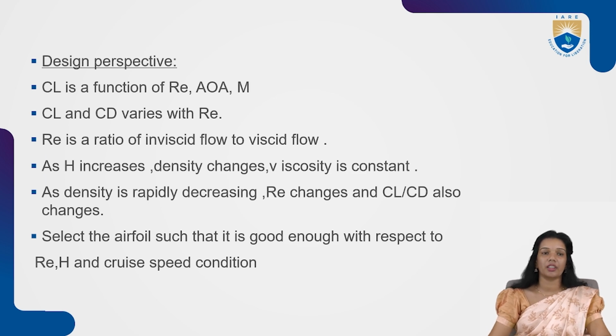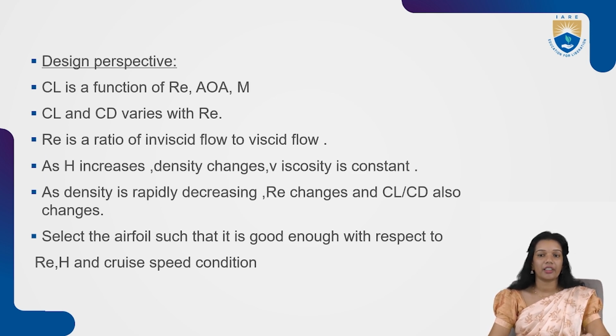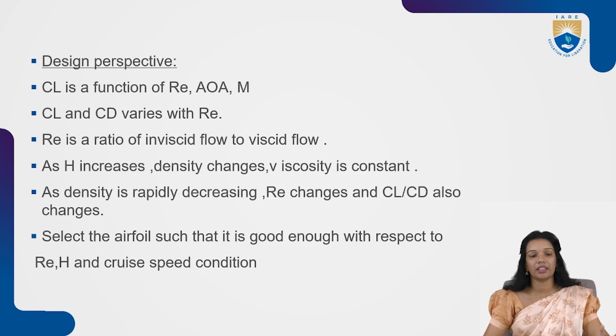Either lift to be increased or drag to be a minimum, or CL by CD to be a maximum, or CL to be an increasing number, or stall effect to be gradually a little less, right? So I consider all of these conditions and I design such a type of airfoil, or I select the type of airfoil according to the mission or according to the application of it.